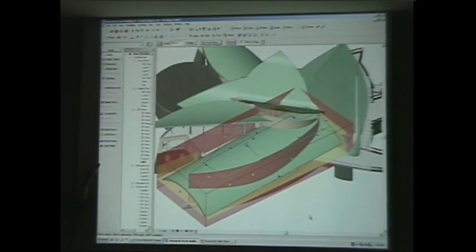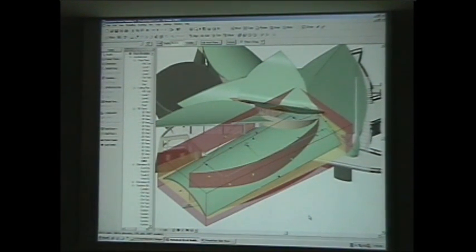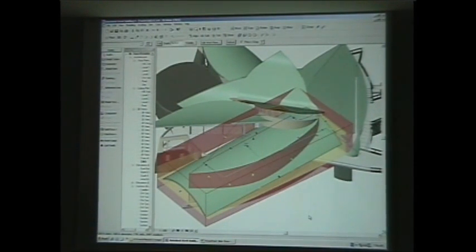So in fact, it's actually very simple structurally, and that's one of the main things I try and do with a lot of these buildings, like that childcare center where all of the walls are curved and canted. A lot of them have holes cut in them and all sorts of weird things. The building itself is actually just sitting on a rectilinear concrete portal frame, and all of those fancy bits are really just cladding. So relatively easy to build. Same sort of thing here.